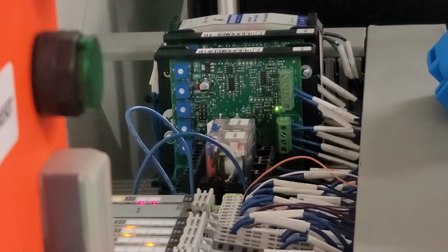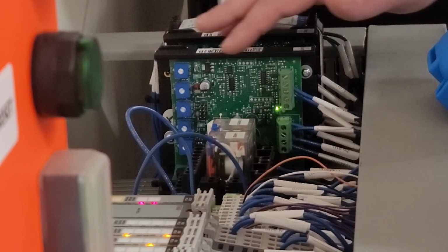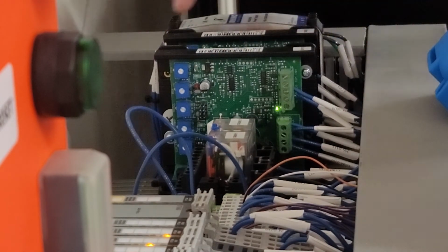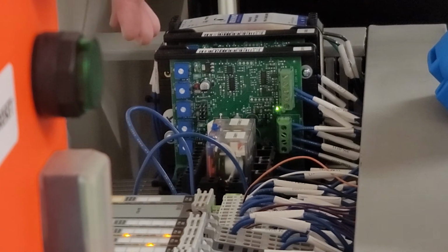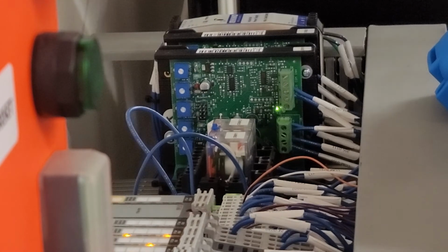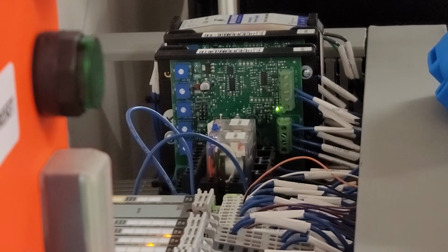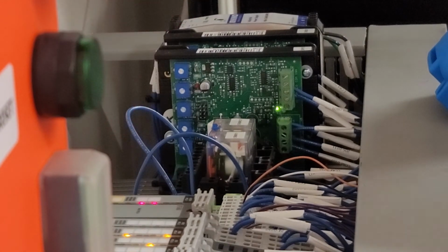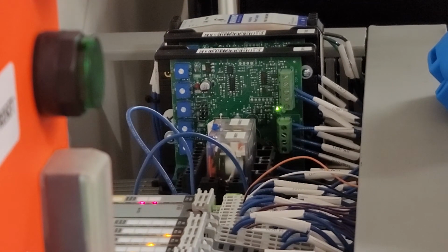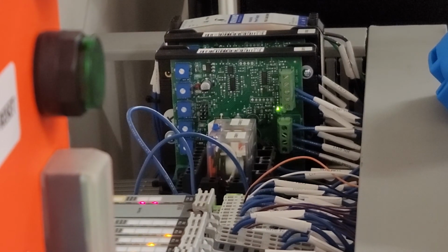I've turned the motors off for right now, but as you can see, these are the DC drives right here, and they have a series of potentiometers along the top edge. When I set these up, I initially set the potentiometers to their highest level, but what may be happening is that our potentiometers are not exactly where they need to be, so their output is not exactly the same.